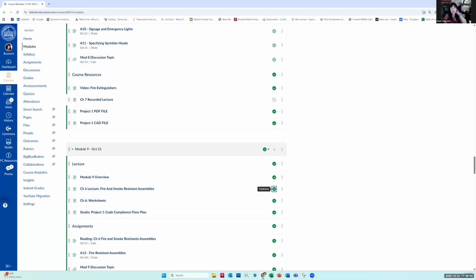It's very similar to the existing suite. The existing suite already has one. If you just mimic that exact door, that would be great. It's 5 feet wide, it goes in 3 feet, and the door goes 18 inches, there's the door. So it's like a little 5x3 recess. It's already in the existing suite, if you go look at it. If you did all the doors like that, that'd be just perfect, because then you have no risk of infringing on the 44-inch corridor.